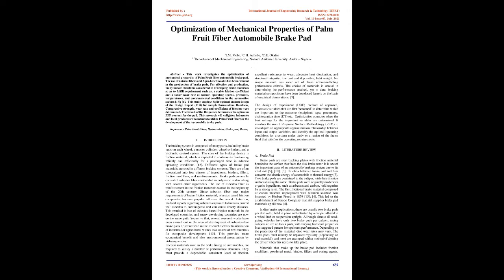For effective pad production, many factors should be considered in developing brake materials so as to fulfill requirements such as a stable friction coefficient and a lower wear rate at various operating speeds, pressures, temperatures, and environmental conditions in the automotive sector. This study employs split optimal custom design of the Design Expert